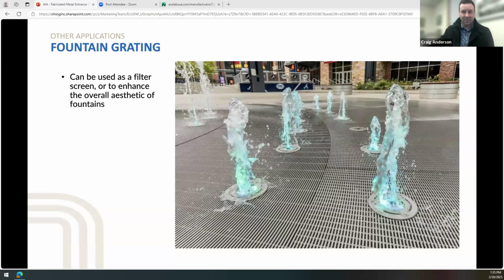There's other types of traction safety products that can be applied to the surface. In this application, it's a very public space. You know, there needs to be a little bit of grit. You can apply a sandblasted finish to the surface of this. You can apply a thermal metal spray, which we'll talk about in a second. And there's a couple manufacturers that have developed different grades of thermal metal spray, so that even if you're walking on this type of material with bare feet in a public space, or thinking of a child walking over this in a public space in a splash park, they're not going to scuff up the bottom of their feet, but they're going to have enough grip to be able to walk around.